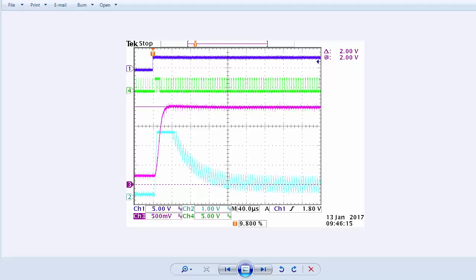So, for simplicity, I would suggest using the open loop sequence to get close to the set point, initialize the compensator error history and output history, and then regulate closed loop going forward from there. This would be a very nice solution, very practical, sensible, and easy to implement.